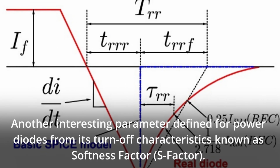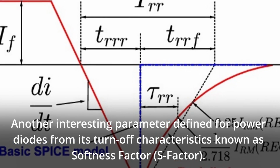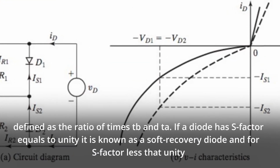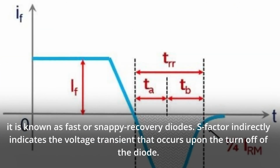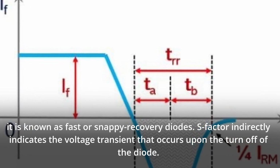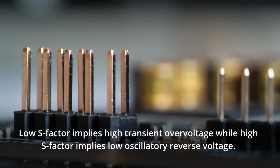Another interesting parameter defined for power diodes from its turn-off characteristics is known as softness factor, S factor. Defined as the ratio of times tb and ta. If a diode has S factor equal to unity, it is known as a soft recovery diode, and for S factor less than unity, it is known as fast or snappy recovery diodes. S factor indirectly indicates the voltage transient that occurs upon the turn-off of the diode. Low S factor implies high transient overvoltage, while high S factor implies low oscillatory reverse voltage.